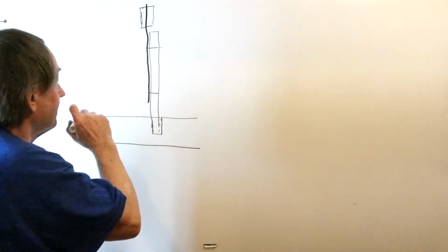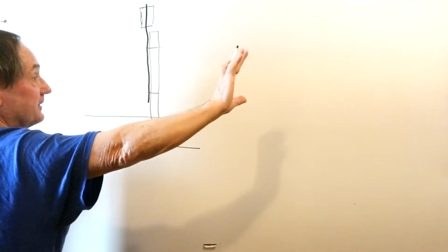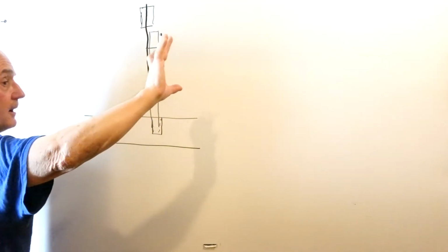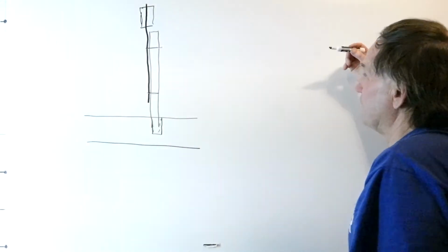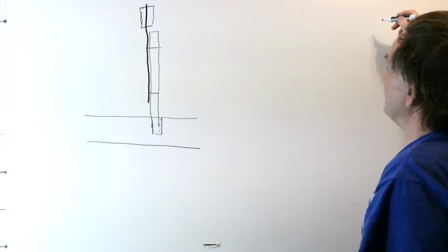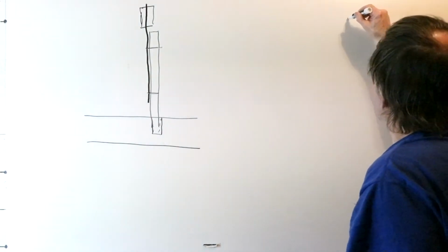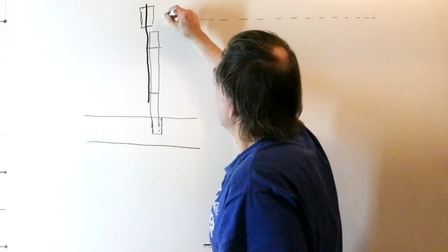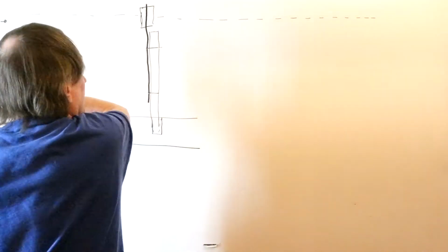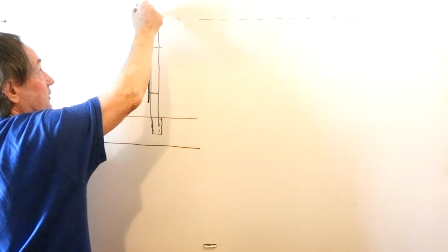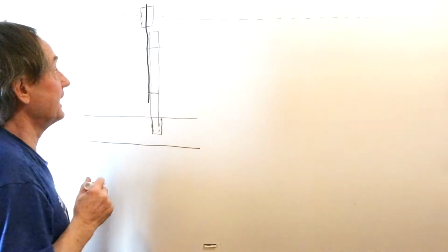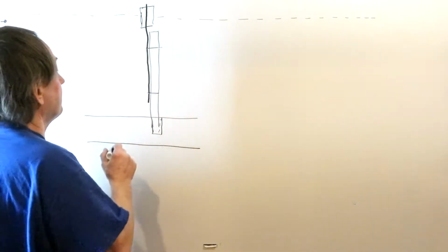Then, back at the observation point, point A, we sight with an auto level and get a tangent, sighting a tangent out away from the reference point. We move the target up and down so the center of the target is in line with the tangent line.